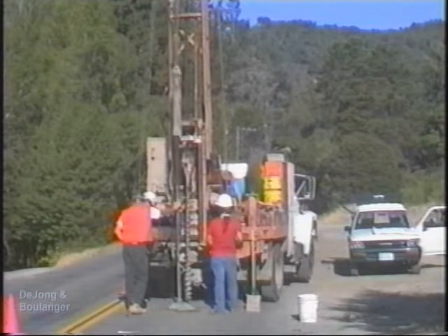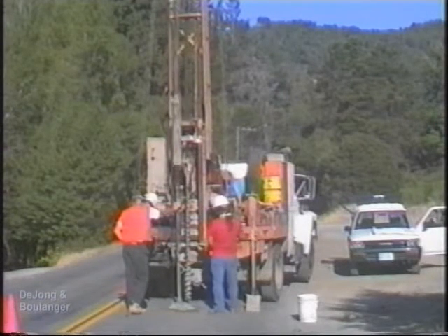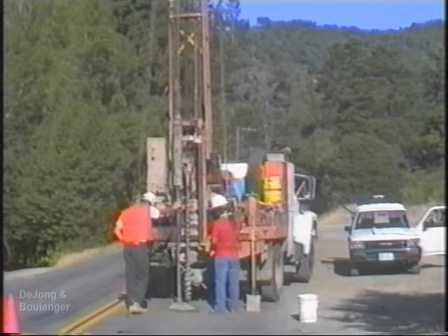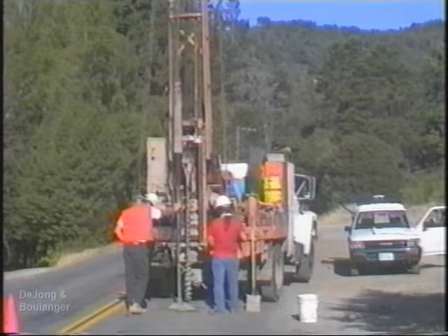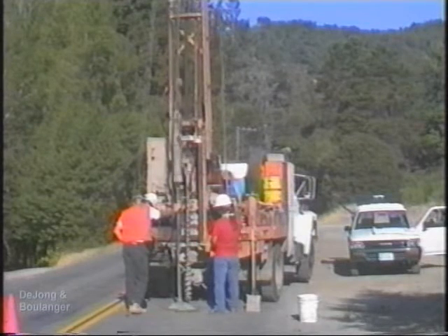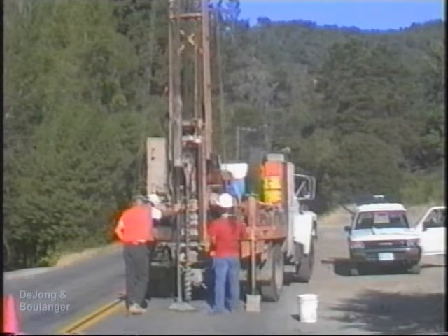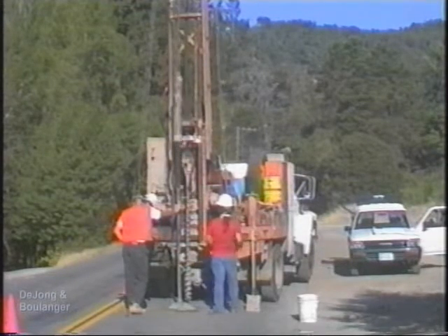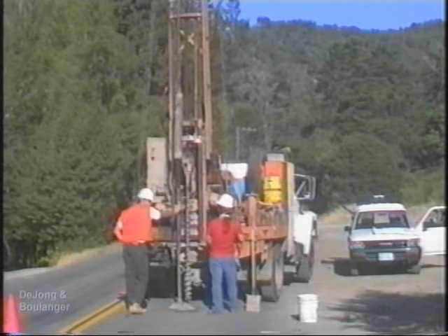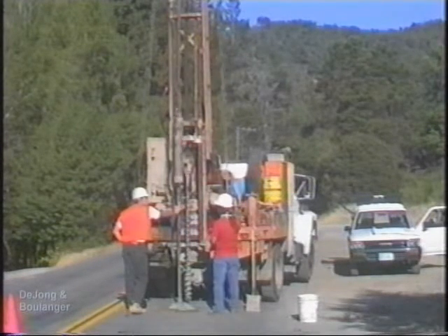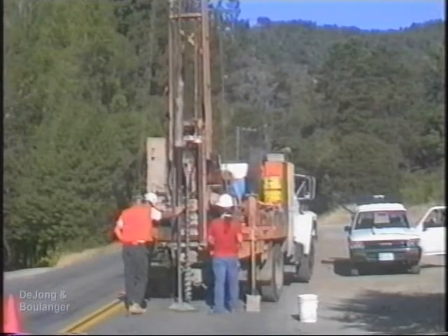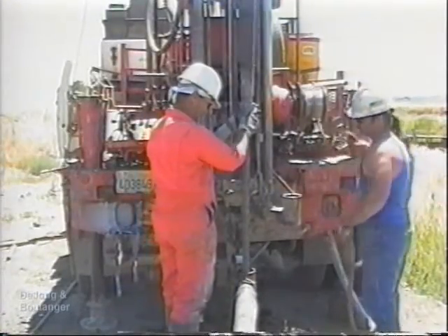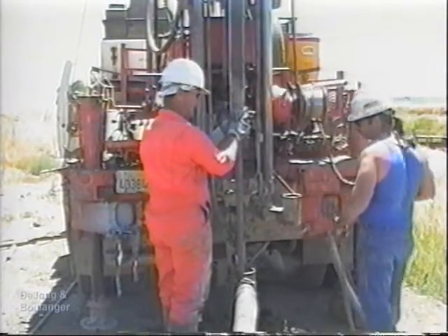The amount of energy delivered is dependent on many variables, including the type and weight of hammer, distance of free fall of the hammer, size and length of drill rods, tightness of connections, weather, and operator. If using a cat head and rope, the energy also depends on the condition and type of rope and the number of wraps around the cat head. If using a trip hammer, the energy also depends on its condition and type.